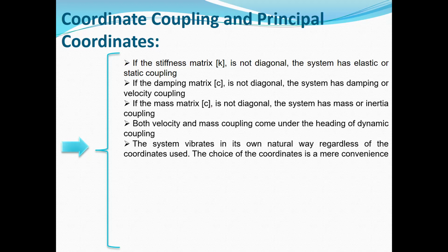I mean, by changing the coordinate system, the response will remain the same, the characteristic of the system will remain the same. I mean, the natural frequency is the same, and when you solve these equations, you will extract the same natural frequency or the same eigenvalue for your system. But definitely by changing the coordinates, you can change the difficulty level of your equations.